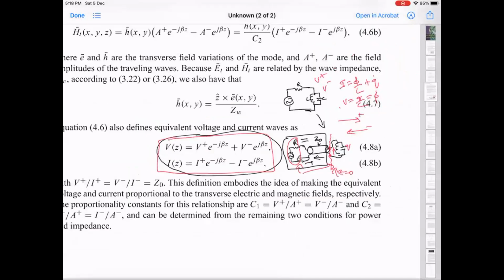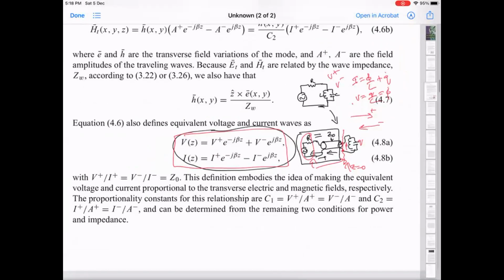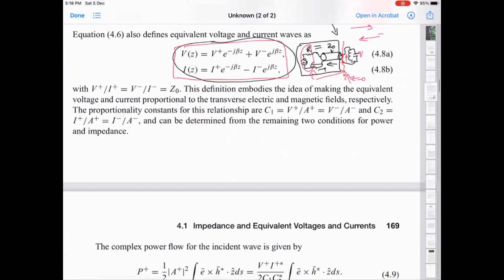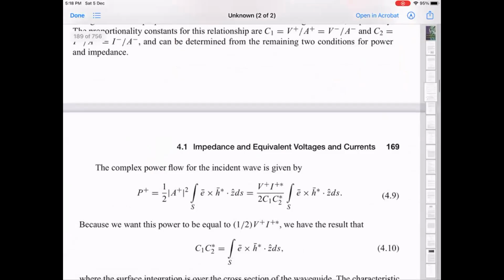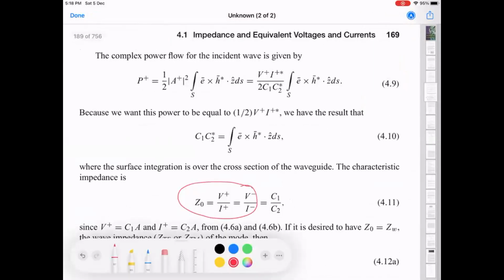And this, I guess it's also mentioned here, but one of the interpretations to understand what this characteristic impedance is really telling you is the ratio of the voltage and current along any point in the transmission line, but not just the full voltage, it's the voltage going right. So it's the amplitude of the voltage wave, right?